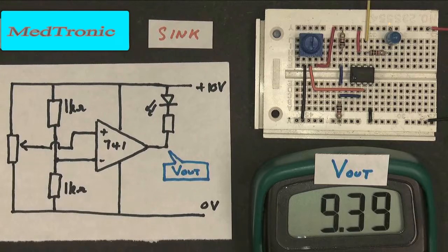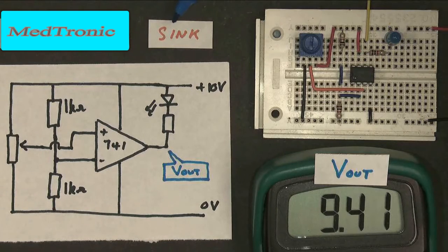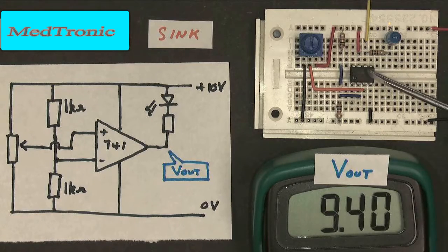And now we're looking at the idea of a current sink. A sink is something like a sinkhole where things go down, or the sink in your kitchen where water goes down the drain. I've rebuilt my circuit. Here my LED is now attached to the positive rail. Here's the positive, it attaches to the LED, and then the resistor goes along into the output of the op-amp. That doesn't seem to make sense, because surely an output should give things out.